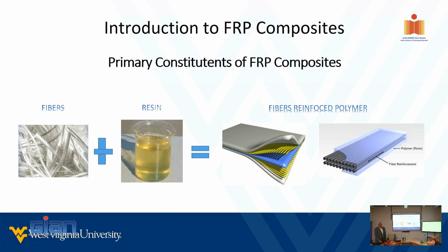Remember that. Manufacturing of a composite is far more difficult than manufacturing steel. It's a very sensitive operation. So that is another area we are struggling with, how to standardize the manufacturing. But once you standardize manufacturing, it's not very difficult at all. The capital cost of equipment is almost nothing. Yes, there is a cost, but maybe one-tenth of steel, for example. So don't overuse fillers.